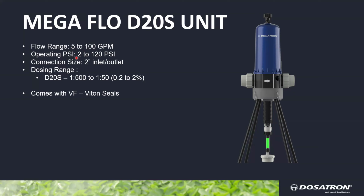We can also operate at a low PSI of 2 up to 120. Our connection size is 2-inch inlet and outlet, and we have a single injection range for this D20, and that is 1 to 500 to 1 to 50 or 0.2 to 2%, and it comes with standard Viton seals.